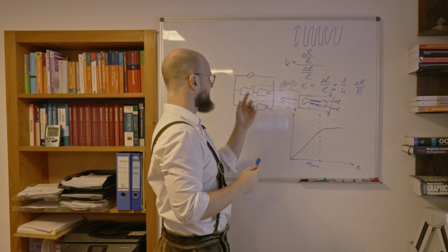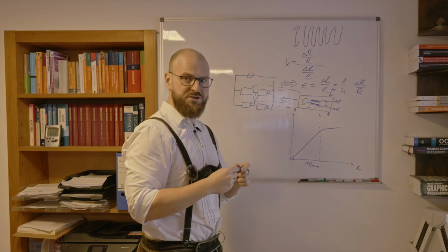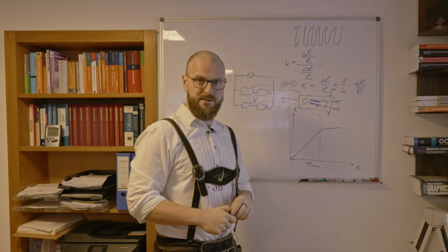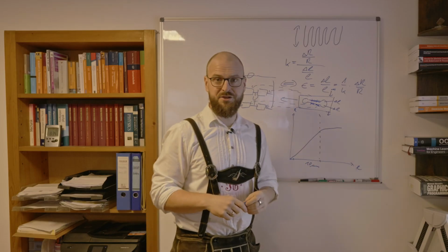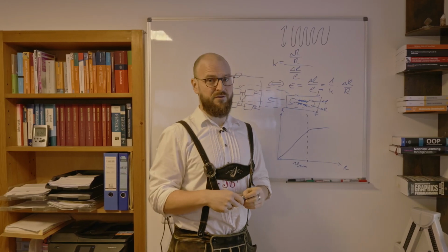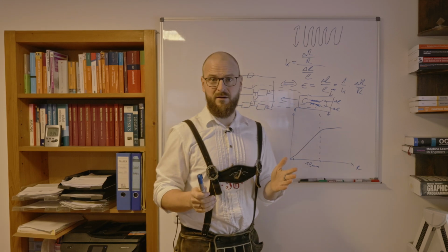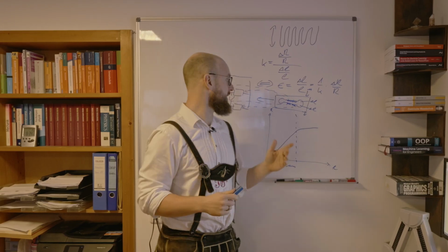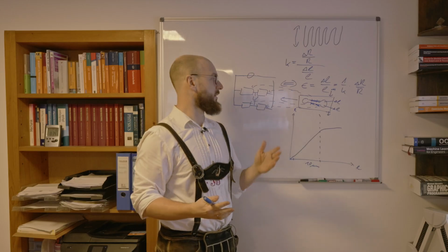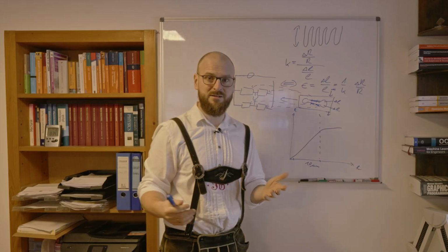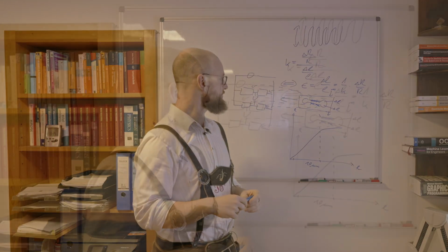which gives us a voltage directly proportional to the resistance change, and therefore to the elongation or to the shortening of the strain gauges. One could imagine a lot of other ways of electrical application, kind of just using 2 resistances depending on strain gauges and so on and so on. But the most typical way would be to use 4 strain gauges which change.